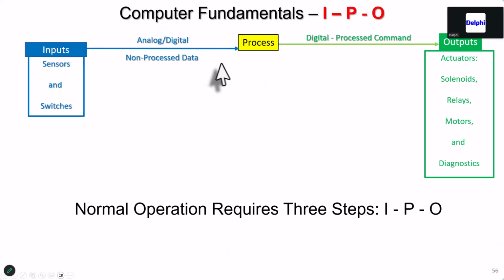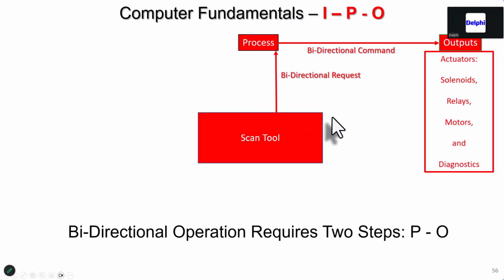Tips for running them. This is my common thing that I share with everybody. I get calls all the time: I can't get this monitor to run. No, you can't get this readiness flag to set. There's monitor tests that you can't get to run. They say, yeah, but it worked with my scan tool. Well, here's what happens when you use your scan tool.